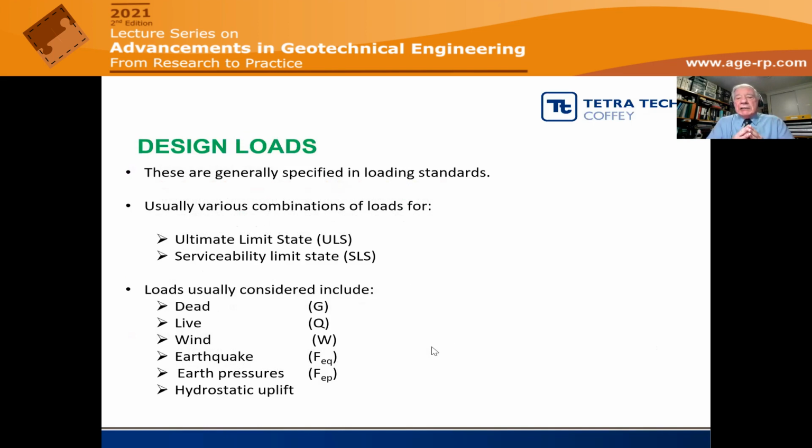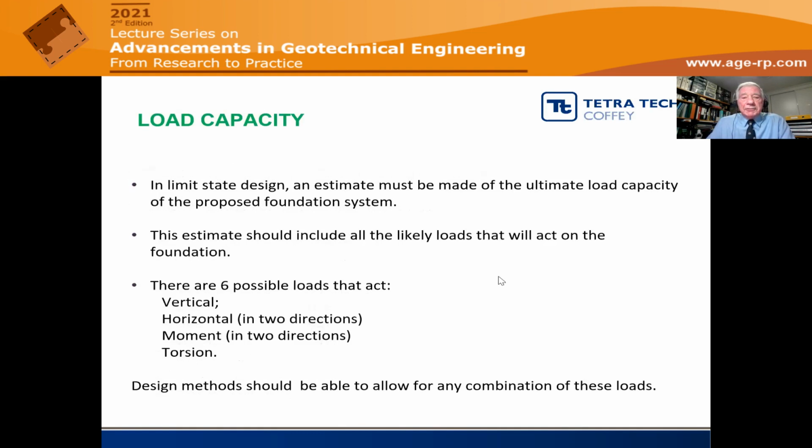In terms of design loads, these are generally specified in the loading standards. We are generally provided with ultimate limit state loads, which are for failure assessment, and also serviceability loads. There are various components of load, which I've listed here. In general, we rely on our structural colleagues to provide us with those numbers so that we can then start our foundation assessment from a geotechnical viewpoint.